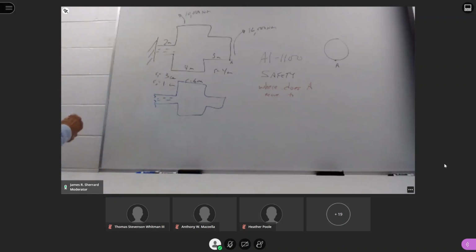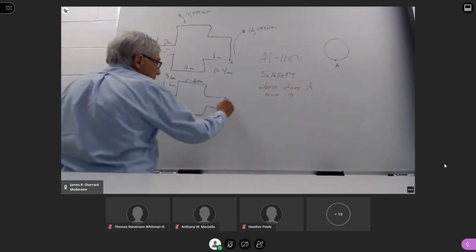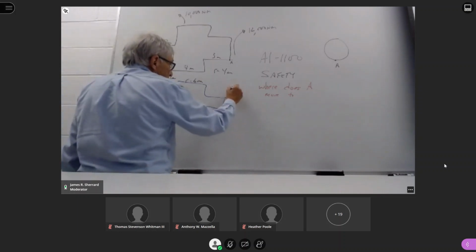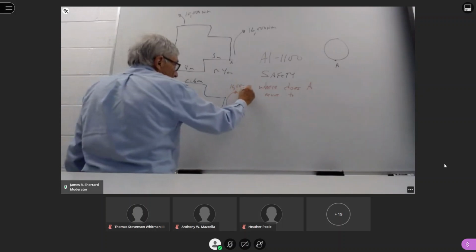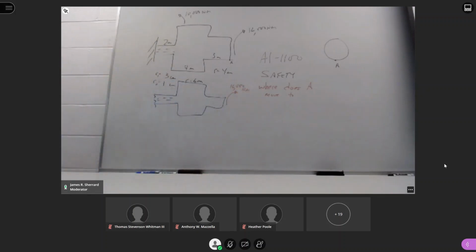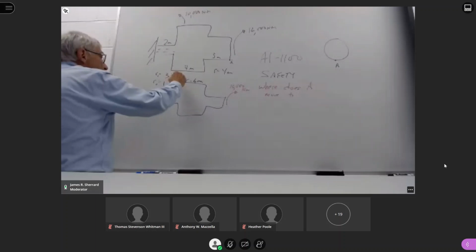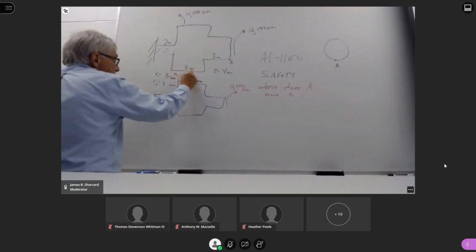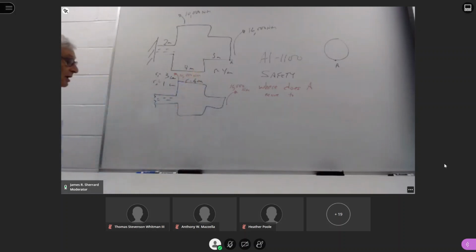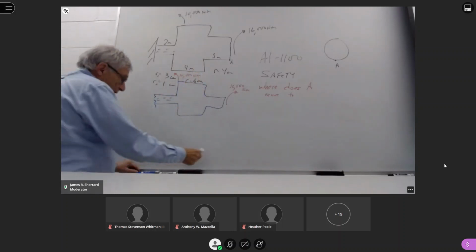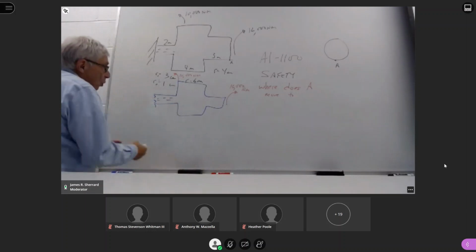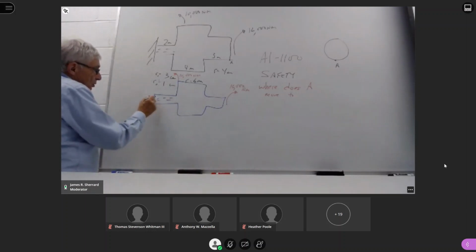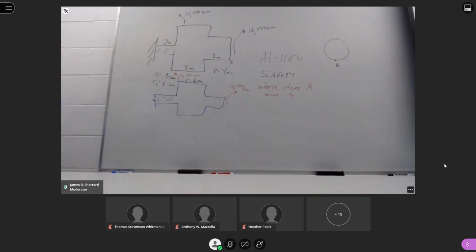So we sketch the member. We draw on any given forces, moments, torques, couples. So we have a 16,000 Newton meter one on the end. And then at this first intersection, we have a 10,000 Newton meter. We only have one attachment point, which is where our member is attached to the wall. And this is the only point that we can add forces, moments, torques, couples.